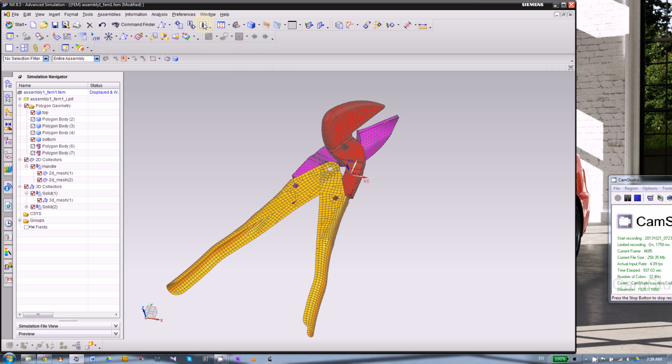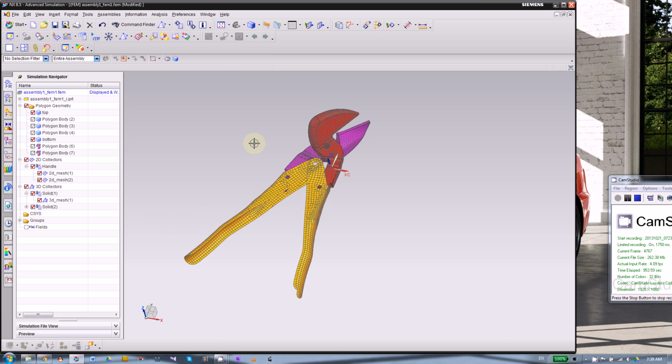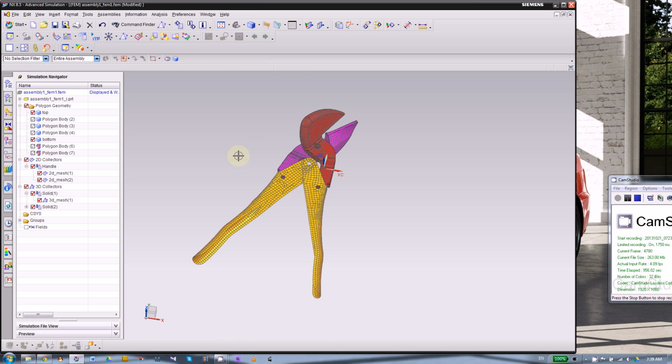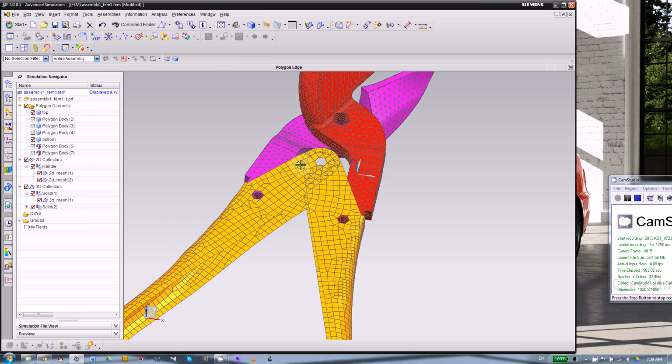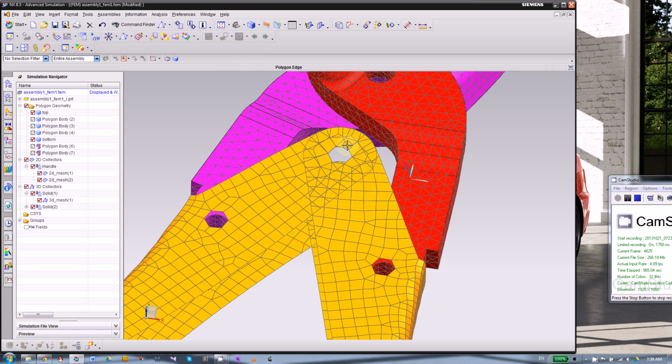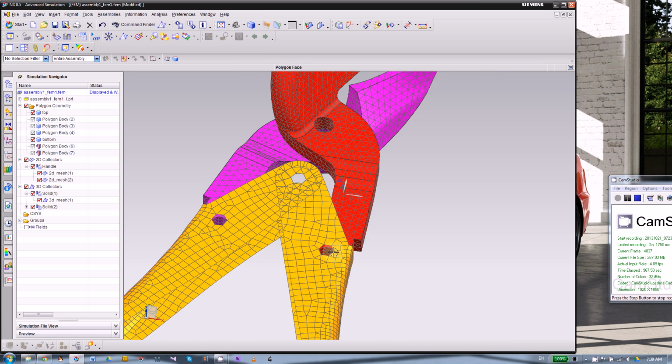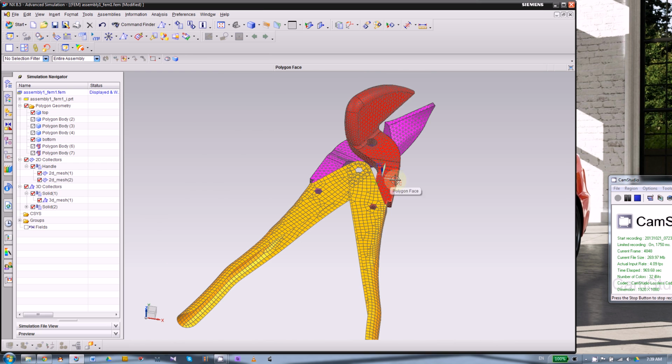Then we came to the fan. We created 2D mesh based on the middle surface of the handle. Then we created a 3D mesh based on the 3D parabolic tetra. That's all for today, and we will continue doing fan for the next week. Next week we will create some spiders and connect them together. All right. Thank you very much.